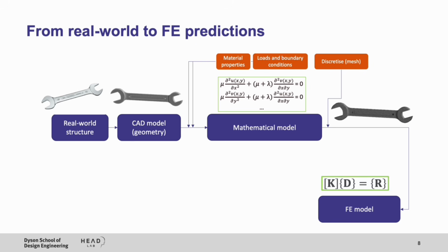So by using finite elements to discretize the domain, we can turn our equations into these sorts of equations which are easier to solve, and therefore we can look at really complex geometries, material properties, and boundary conditions, and still find reasonable predictions for our problem. Like here I'm showing the displacement field, or total displacement field, for our spanner.